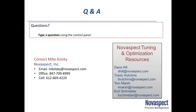There's a question here that says, when normalizing the process variable, what should be used for the maximum? I hope I'm understanding the question correctly. All I'm doing is switching the PV change from engineering units to percent of scale.